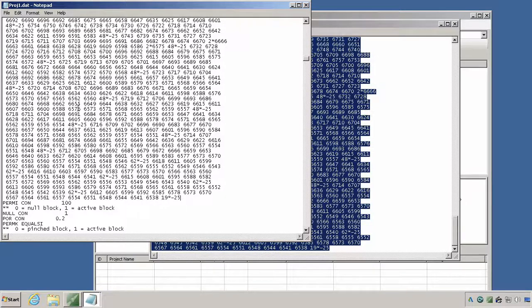So the dtop file is basically the grid depth minus 25. In our simulation file, we're defining depth at the grid center, but dtop is located at the top of the grid block, so we needed to subtract half of the grid block thickness.